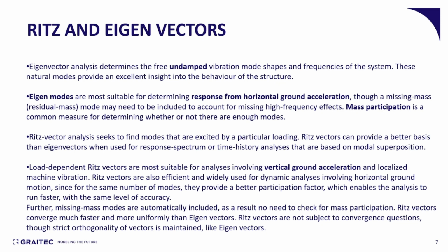The load-dependent Ritz vectors are more suitable for analysis involving vertical ground acceleration and localized machine vibration, which is obviously out of the scope of this presentation. Ritz vectors are also efficient and widely used for dynamic analysis involving horizontal ground motion, since for the same number of modes, they provide a better participation factor, which enables the analysis to run faster with the same level of accuracy.